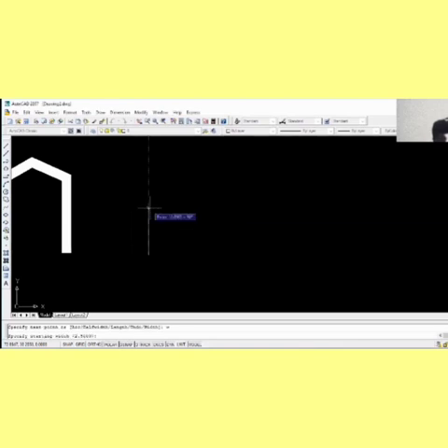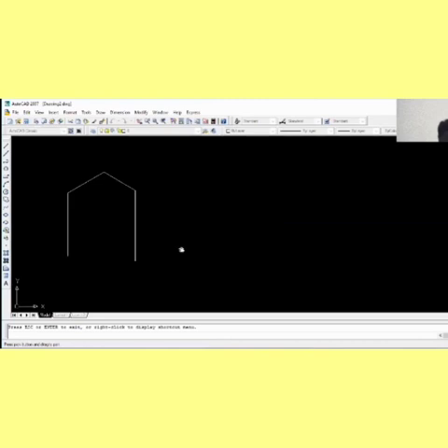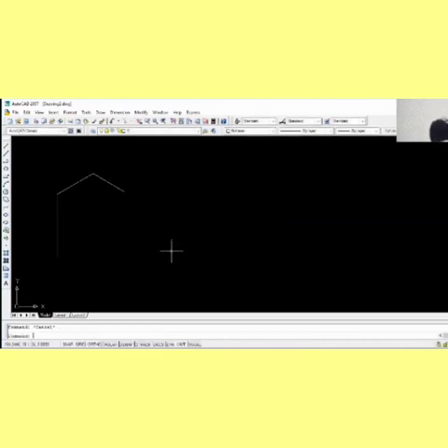Enter. Now it says specify the starting width of 0. Let me use 0 and then enter. It now says specify ending width. Let me also use 0 and then enter. So now I've returned back to the original thickness. So now you can see it, still with my polyline command, then escape. So now P, enter, and then move. Move.